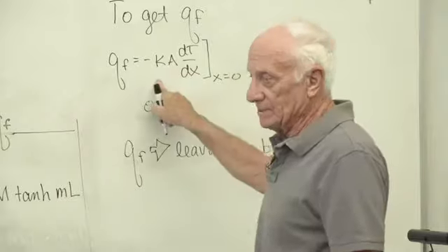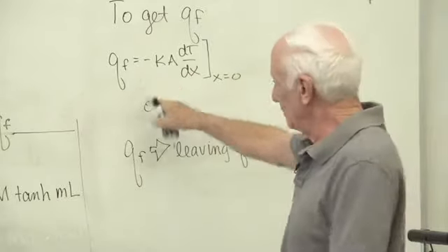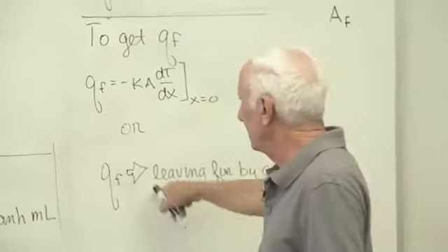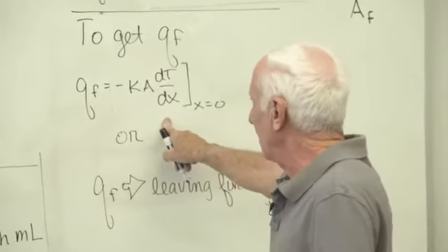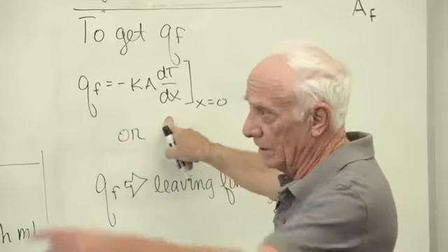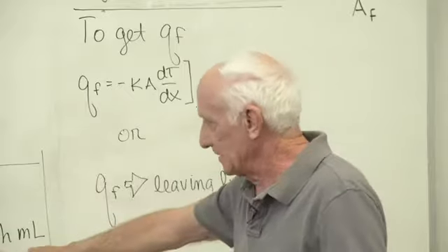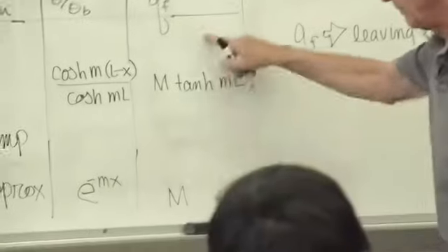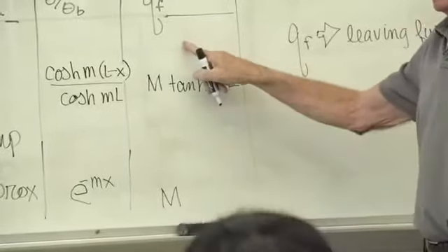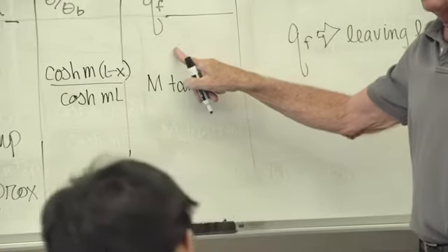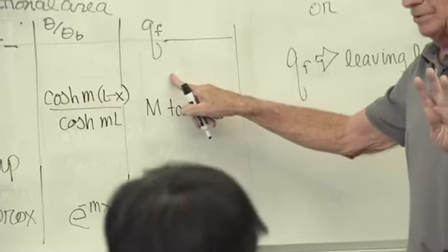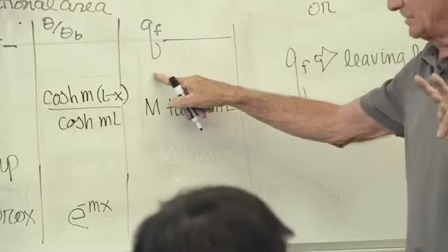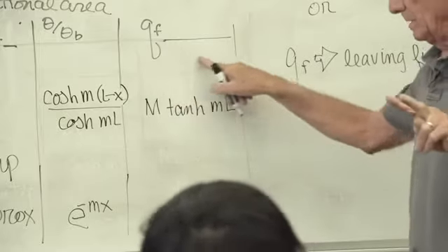This is the way the textbook does it. It's easier. This way is an integral over the surface area of the fin. That's the easy way out. If you want to find QF, look at the conduction through the base. That's what he did. That's where these quantities here came from. This one here is pretty complicated. He's got hyperbolic sines and cosines, 4 terms: 2 hyperbolic sines, 2 hyperbolic cosines, and this one. That's a big one. This one's the easy one.